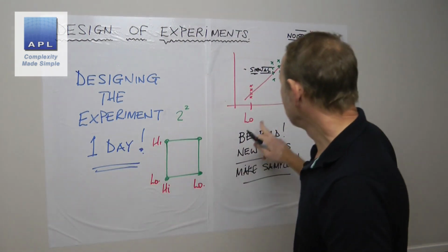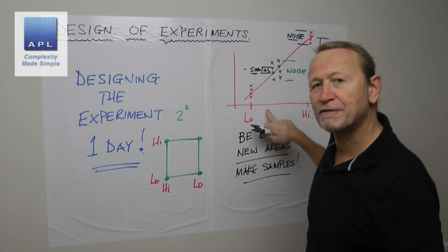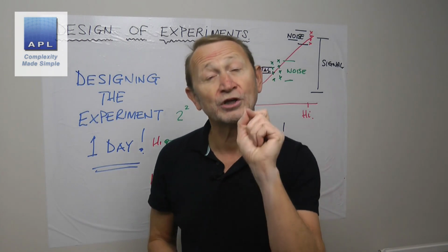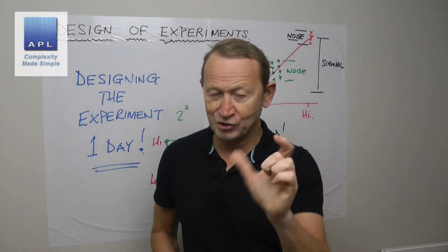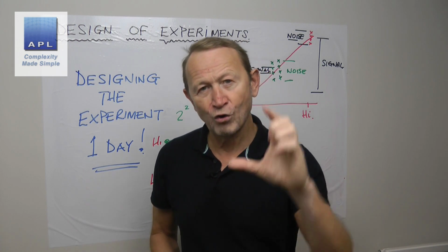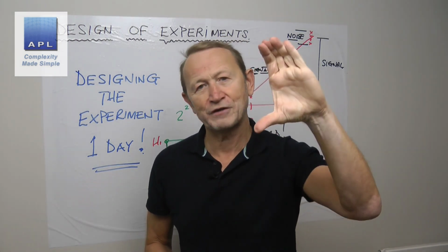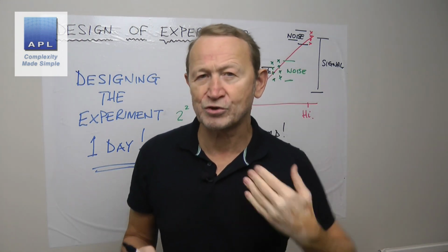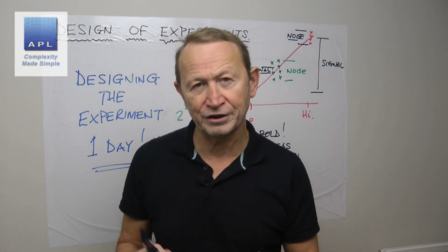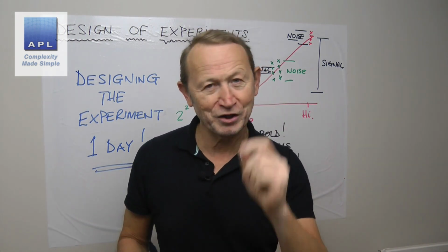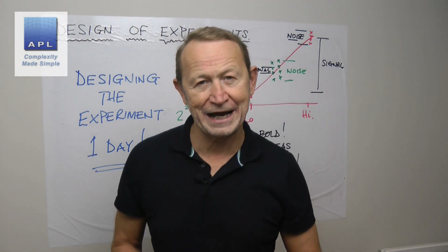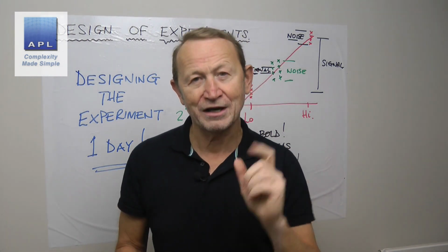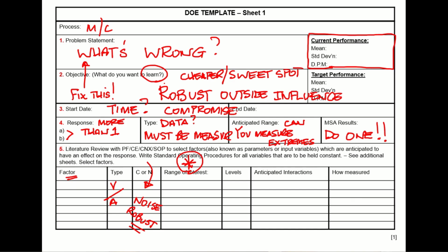It could be that you might have to do a little bit of one factor experimental work to decide whether the extremes will work for you or not. That's why this takes some time. All of the tests have to work. So if it's 16 tests in your 4-factor DOE, all 16 rows have to produce data. They all have to work. So you want to make sure this is right before you start. Really important that you get that bit right. You can spend a couple of hours in this box alone. Okay, so let's move on to the next one.